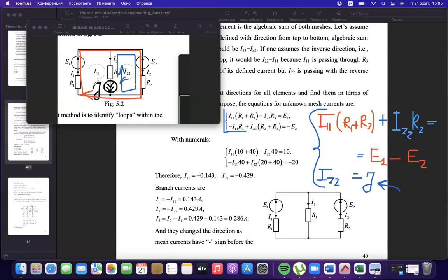If we have a current source J, it decreases the number of unknown variables by 1. And if in the initial circuit we have 2 unknown variables, including J, it will be only 1 unknown variable, only from this equation. Such a specific thing. All equations for the solution we should take outside as a mesh outside the J.